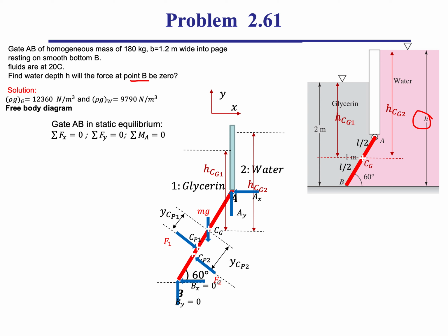So if I decide to do sigma Fx and sigma Fy, I have this force unknown and the reaction at A unknown. So I have more unknowns than I need. One way to go about this is if we pick point A and we do a moment around point A, we automatically get rid of the reaction at point A because the moment arm is 0.